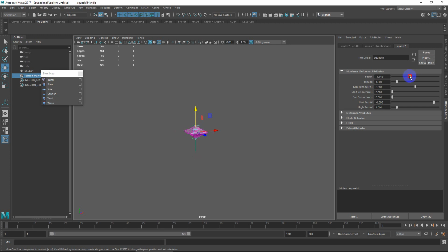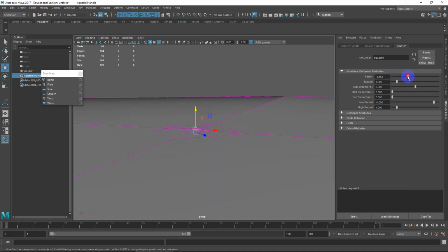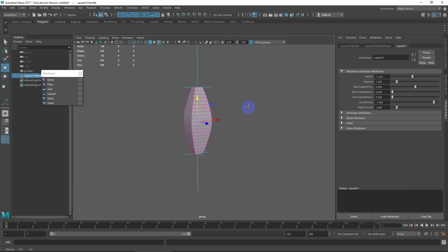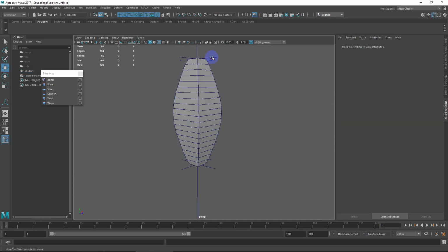So like in a cartoony character or any object that's animated in a cartoony fashion, you'd want to maintain volume, but you just want to stretch it thin or make it short and squat and fat and plump. So yeah, that's one way to create a shape like that. Oops, I am going crazy here with the slider. There we go. And again, like all these, you just simply click on the mesh, you can go delete by history, and it makes that a permanent part of the model.